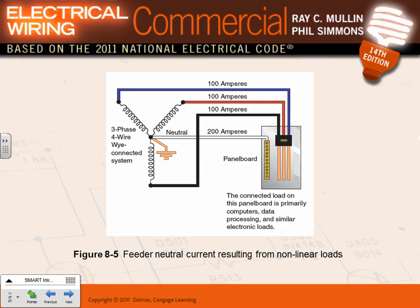Okay, here's a situation where I have a 100 amp panel. This is really cool. I have my 100 amp panel, and can you guys see the neutral conductor here? The neutral is 200 amp. This is if you have a panel that feeds servers, a room like yours here, full of computers. That's exactly how they do it, guys. They make the neutral double the size of the phase because of a word called harmonics.